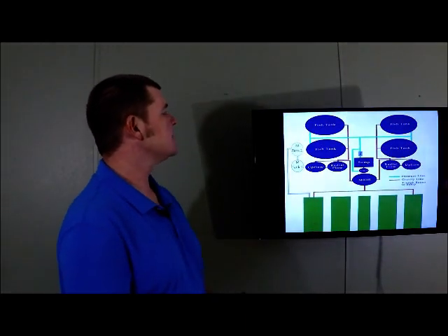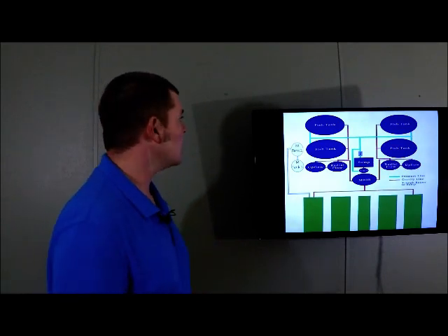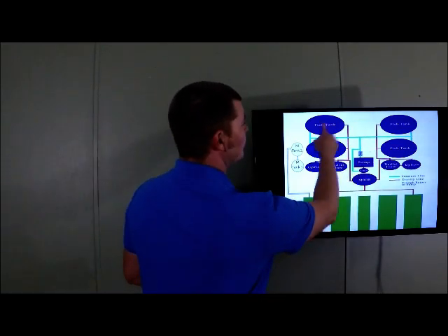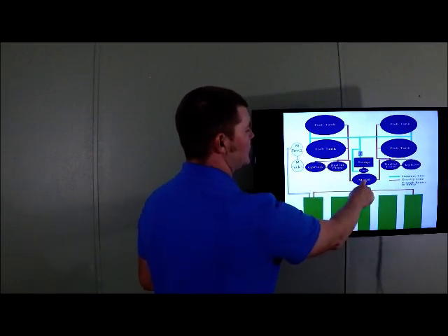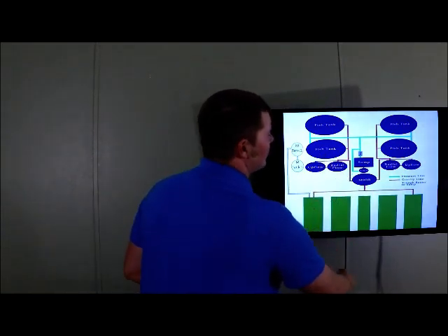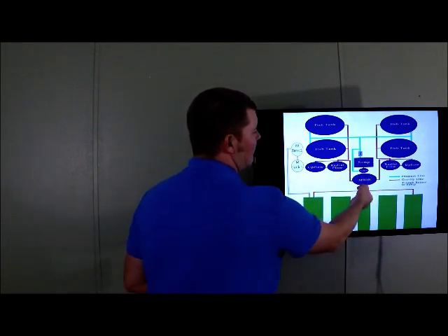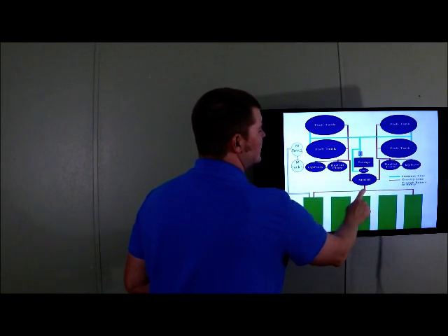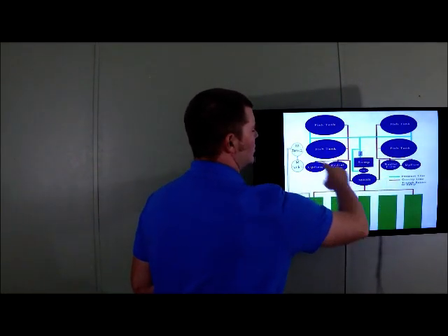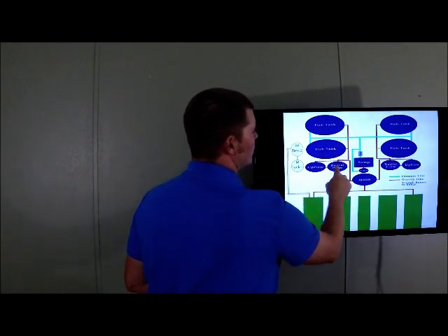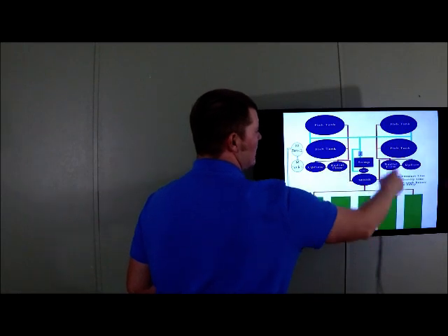Okay, back to this picture, just like I mentioned during the Chatterson Farms talk. Normally, recirculating, we go fish tanks through the filtration, through the biofilter, out to the beds. It wraps back around, comes back, and back to the sump. Well, when we turn that valve and we make this a decoupled system, we have this operating just as a recirculating aquaculture system. Fish tanks to filtration to biofilter, back to the sump, back to the fish tanks.